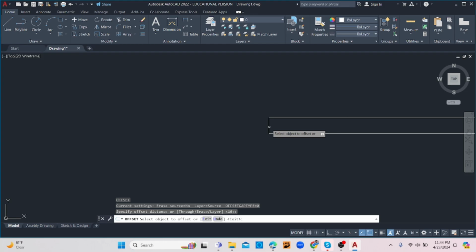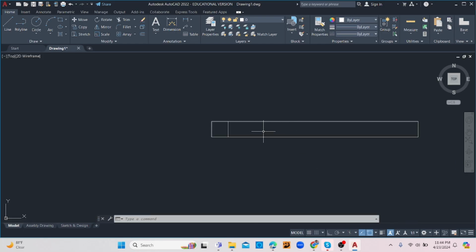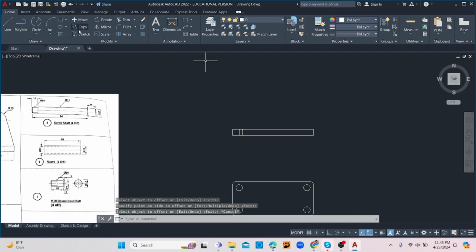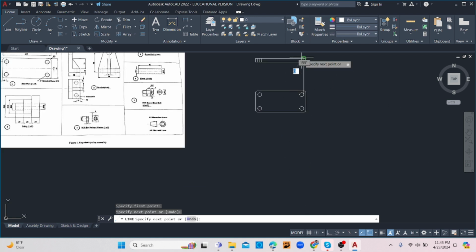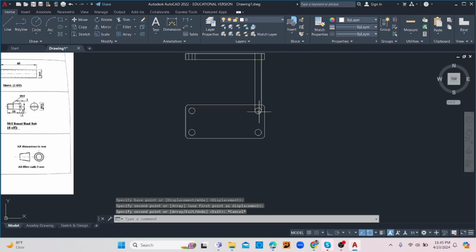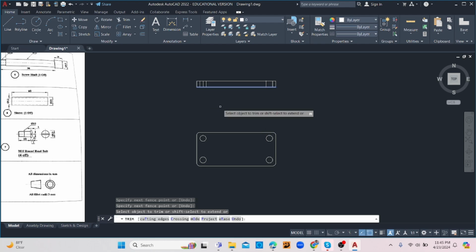in the middle like this, and then to get the whole portion as you're seeing here is to simply offset 5 on either side of the line. So you'll offset 5 on either side of this line here, and then you'll have it. Alright, but since I did this over here, all I can do is simply probably project some lines up to capture that. So there's many methods in which you can use to get that hole in the middle there, if that makes sense. Alright, so that would be that. You can even do one side and then mirror to the other side. The option is totally yours in terms of how you want to approach the drawing.